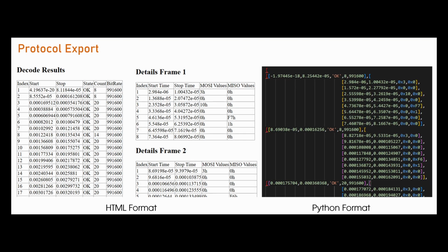The table is also handy for seeing the protocol decode. What's excellent is the flexibility in exporting that to files. There are several choices including HTML, and it prints a nice summary of each frame and then all of the bytes detail. I would say that the output is about as perfect as it could get. Another option is Python format export, which is super handy for comparing the bytes with a test dataset, or for doing things like performance profiling and to see where bottlenecks are.